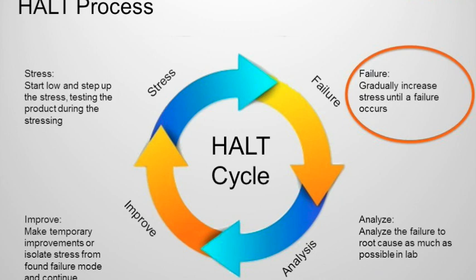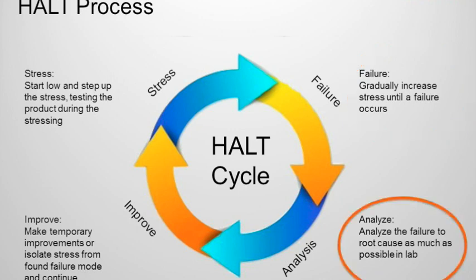You want to make sure you're monitoring the product performance correctly. So what are the important functionalities that you should be monitoring? This is important to have thought about in advance, and this will help you with the next step, which is to analyze. Effectively, what's occurred in the HALT test, you can consider it a crime scene. Something's happened, and we need to start the detective process of understanding it.